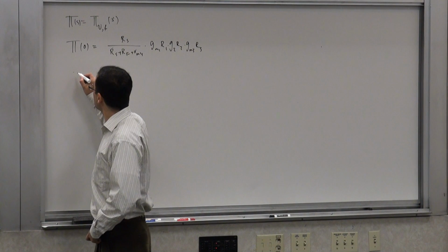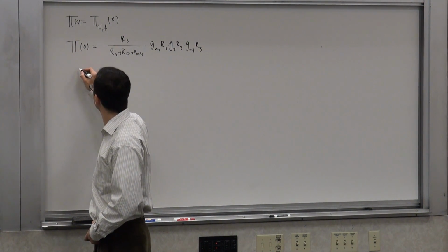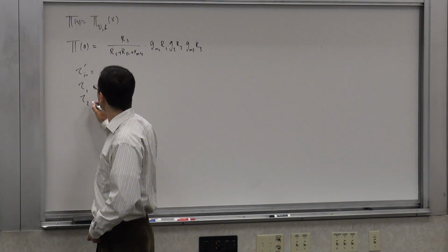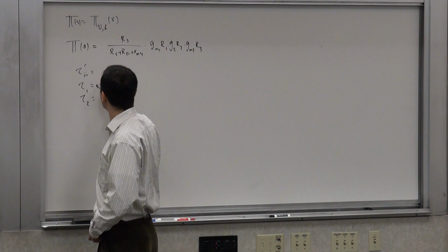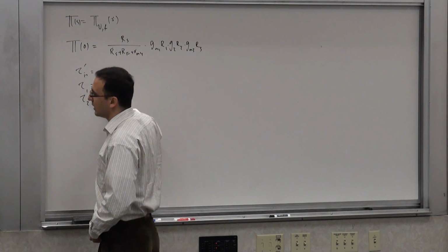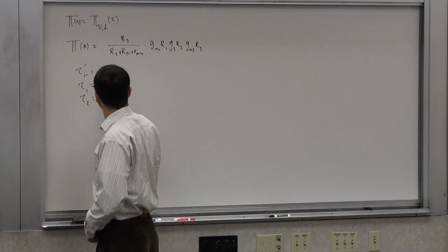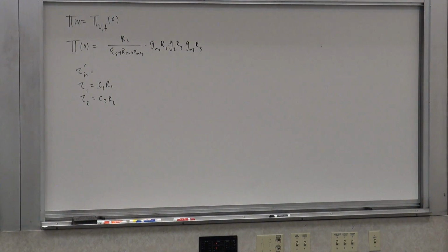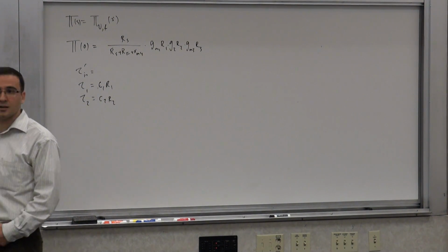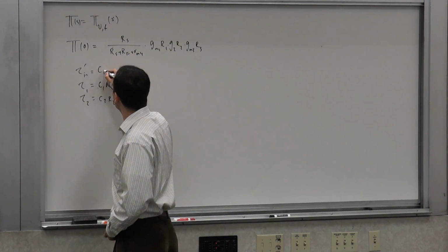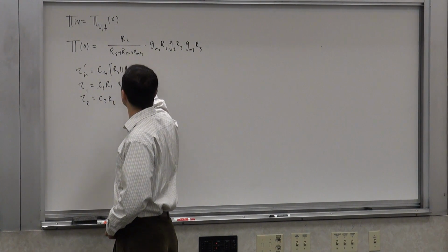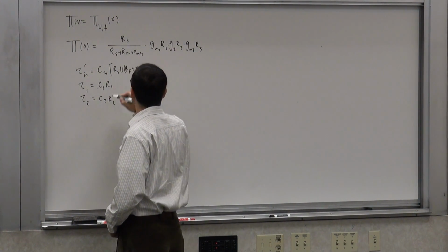So, which one is different? Which time constant is different? Tau in. So it's tau in prime. Tau 1 and tau 2 are the same. So this is basically C1R1, C2R2. But this one's the new tau in. So it's Cn times Rs parallel Rf plus Rm, exactly.